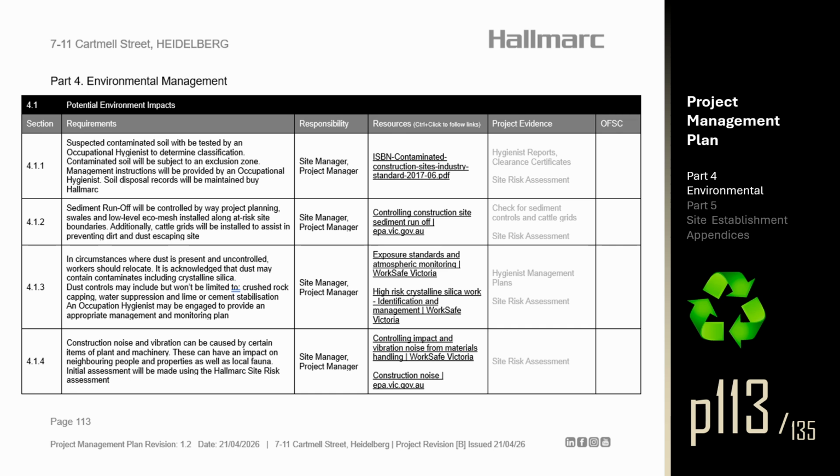Section 4.1.3. In circumstances where dust is present and uncontrolled, workers should relocate. It is acknowledged that dust may contain contaminants including crystalline silica. Dust controls may include, but won't be limited to, crushed rock capping, water suppression and lime or cement stabilization. An occupational hygienist may be engaged to provide an appropriate management and monitoring plan.